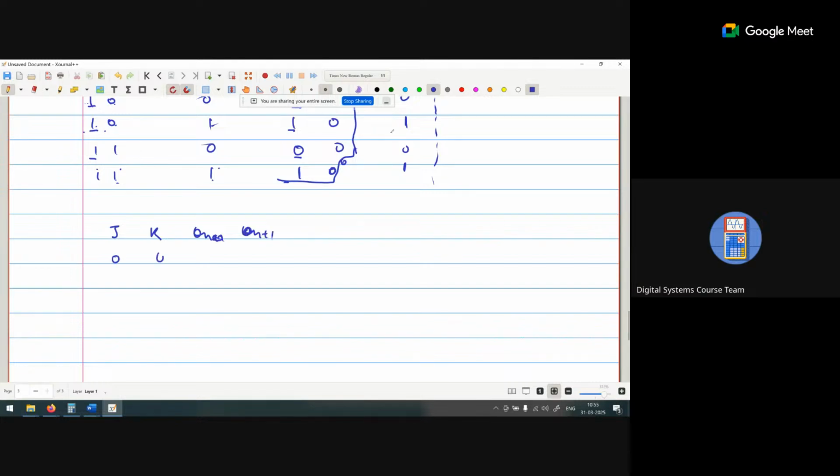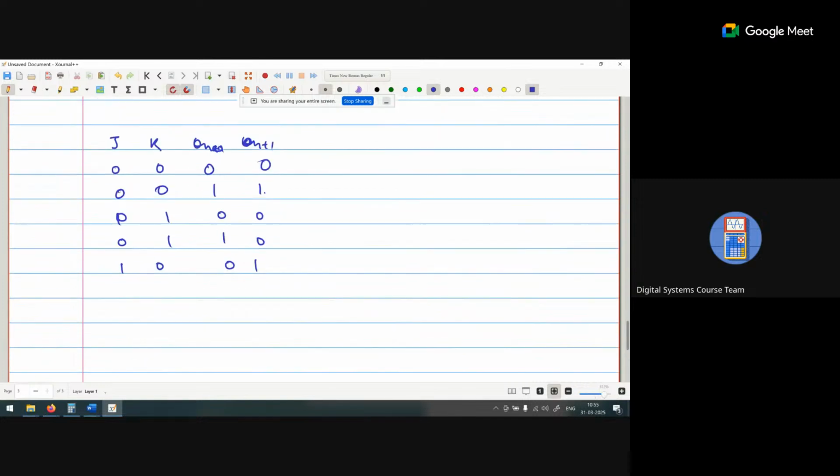So when J K is 0 0, Qn plus 1 is the same as Qn. 0 1: Qn plus 1 is 0. 1 0: Qn plus 1 is 1.